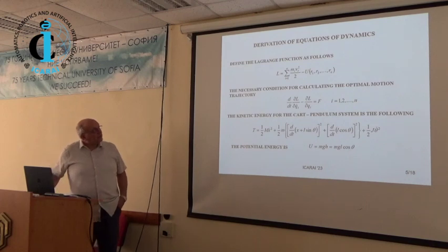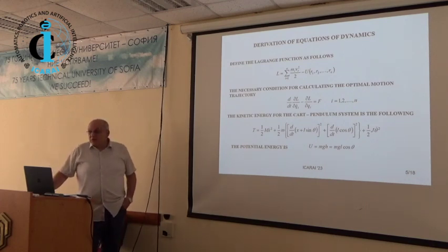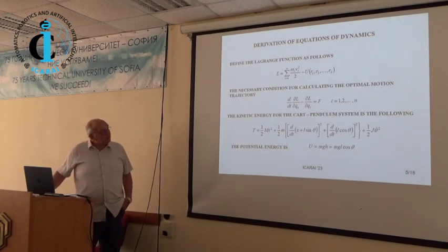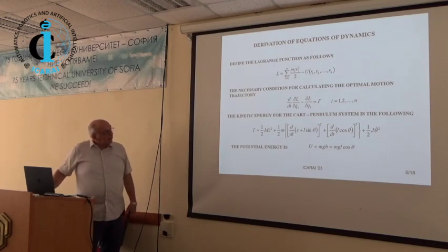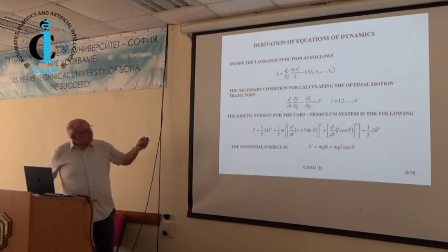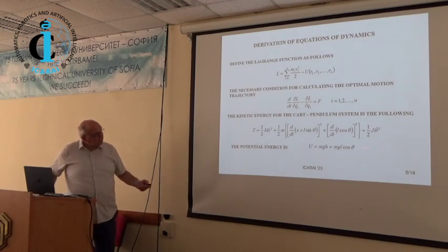These are our variables. To develop the dynamical system of the inverted pendulum system, we use the Lagrangian framework. That means we work with energies, and our main equations are the Lagrange-Euler equations, which are presented here. For computing the Lagrangian function, we need to compute the kinetic energy, which is computed like that.